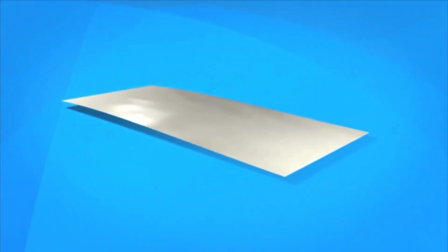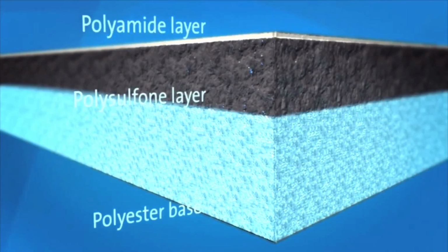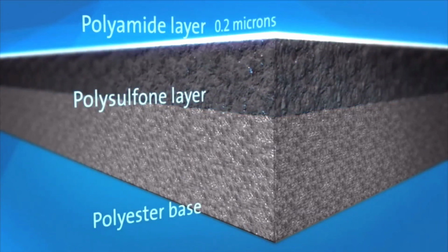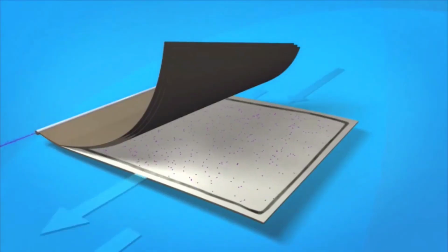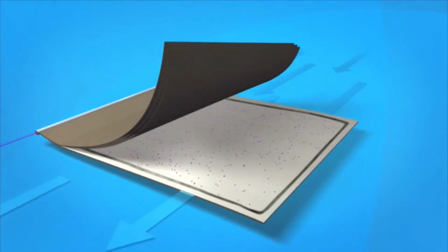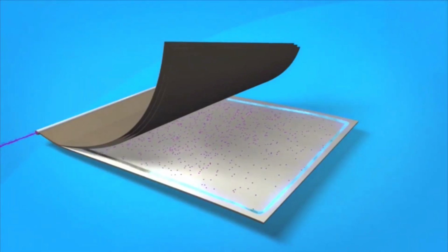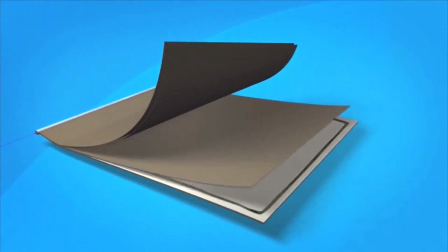Reverse osmosis membranes are constructed from a membrane flat sheet. It is comprised of three layers: a polyester fabric support base, a macroporous polysulfone layer, and a polyamide barrier layer. The polysulfone layer strengthens the very thin barrier layer. This one removes nutrients, chemicals, bacteria, and viruses from the water. The back of the membrane is completely sealed to the edges of the permeate spacer. The membrane sheets are glued along each of the three exposed sides and rolled around the core tube.